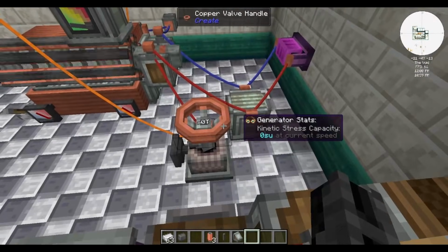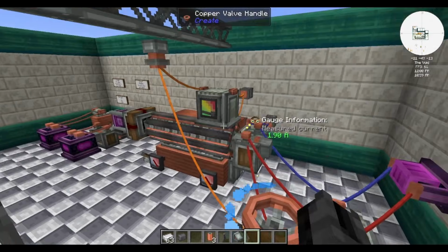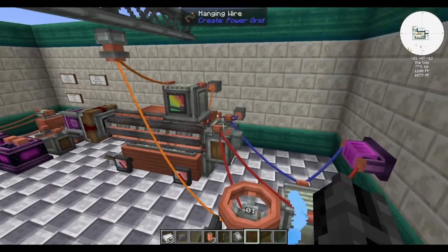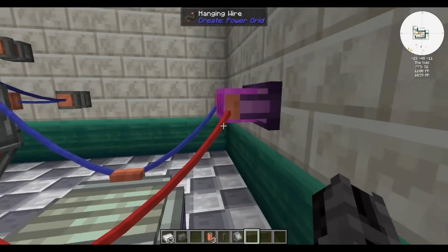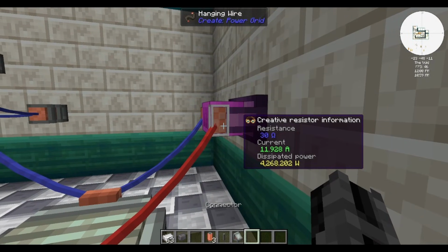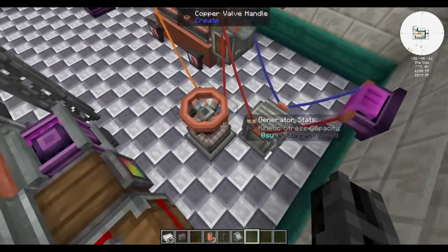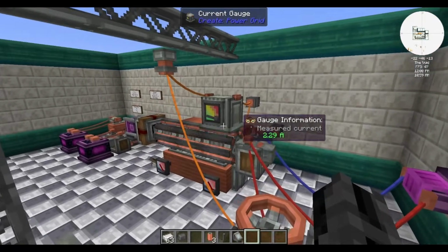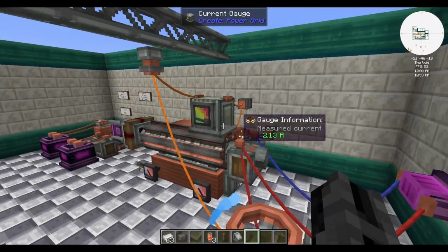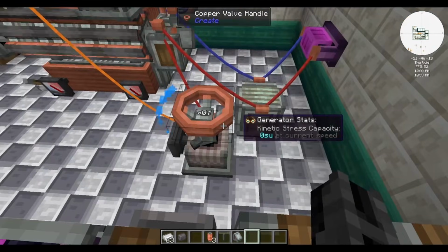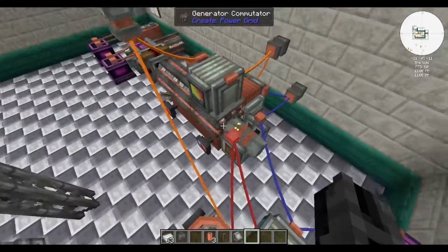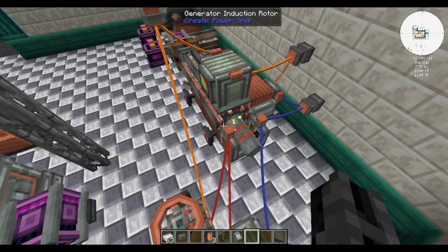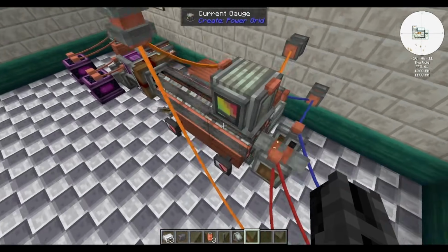If we go above, we not only start wasting power, but our power also starts dropping. So keep in mind, keeping the exciter current at the correct value is worth it, because it keeps the generator stable and producing maximum power at minimum losses through the excitation.